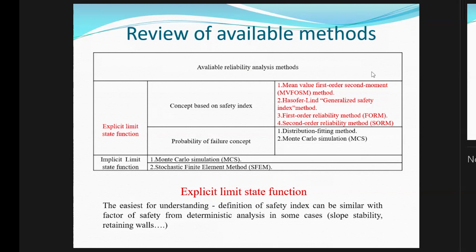We always know that there is some kind of uncertainty in that analysis, and the output of our analysis, like the safety factor against some damage or failure, is a deterministic value, a single number, like a safety factor of 1.5. But if we treat the input values like loading as distributions, like normal or log-normal, then the results of our engineering analysis can also be curves that have a certain probability distribution.